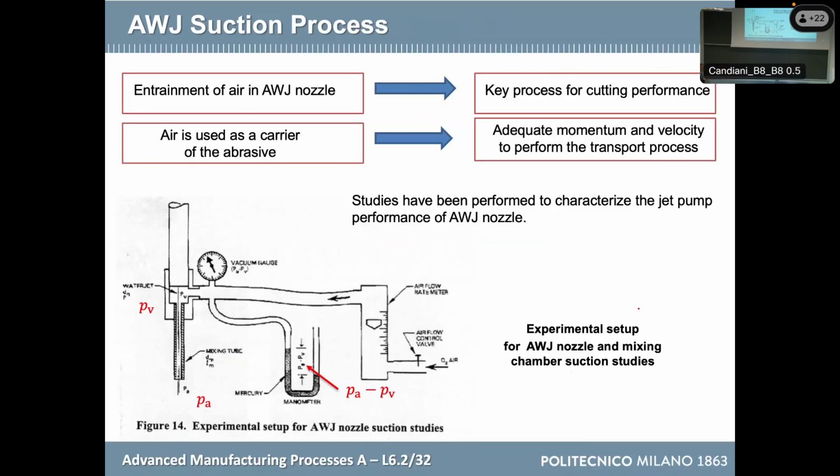There are other ways. There are ways where you have a hot filament, and depending on how much it decreases in temperature, you can have a measure of the flow rate. Or there are some fans. The fans can measure the flow rate, but there is a drawback there because they interact with the phenomenon. So they are changing a little bit the flow rate, even if their resistance is low.